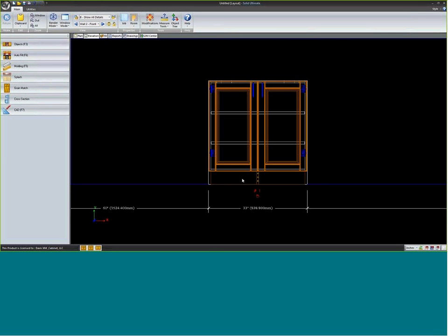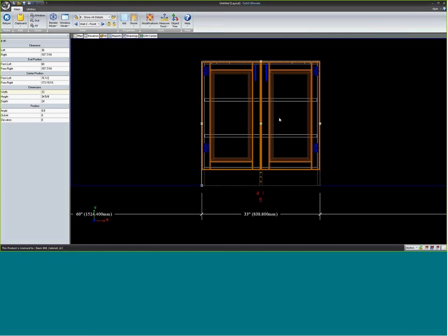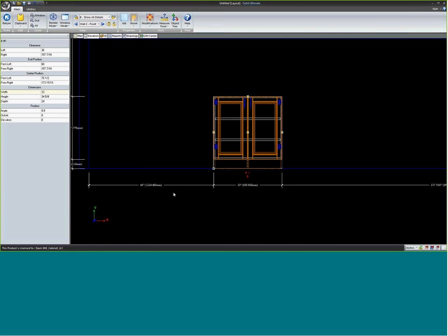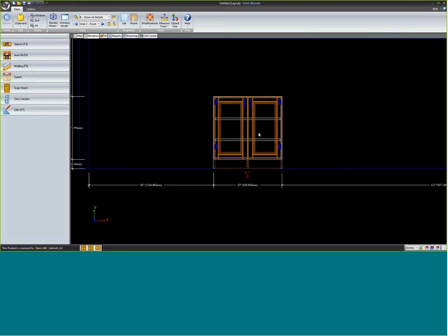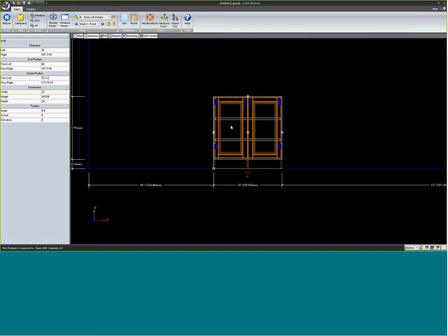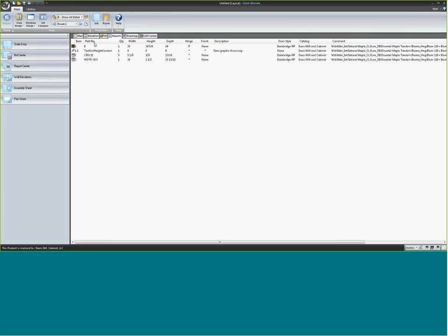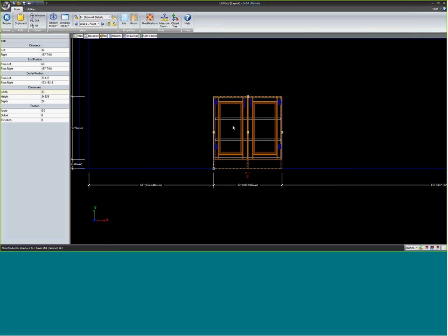If I go back here to my elevation view and click on this cabinet, there's nothing really that's changed. What happens is when I drop a wildcard on that cabinet, this cabinet has had no reason to rebuild or sort of rethink how it's constructed. In order to make it fresh, to recognize this toe kick height that we've added on it, if I click on that cabinet and hit my enter key 2 times, like a double click on my enter,